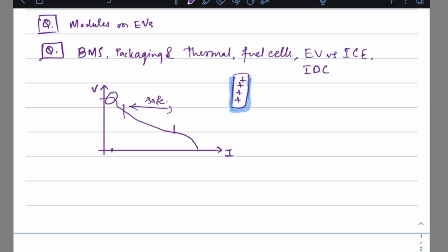The fast charge technologies which are available today will take you really fast from extremely low battery SOC, that is state of charge, to a reasonable SOC, say 30-40%, and then it will slowly charge. So the slower you charge your battery, the better it is for your batteries. If your vehicle knows you are putting it for an overnight charge on a slow charger, which is what you get with your home pack, versus what they call supercharger or hypercharger, whatever, the fast chargers which are there commercially at places like malls.